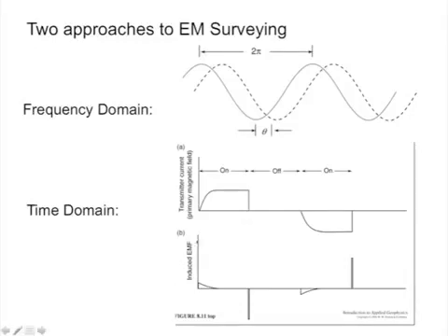All right, and so we'll get the cutoff of the currents, which is the thing that has the smallest delta t. Okay, and so that's going to produce the largest induced voltage, induced EMF, electromotive force. Okay, induced EMF, induced voltage. Right. So the cutoffs are going to produce these big voltages. Okay.